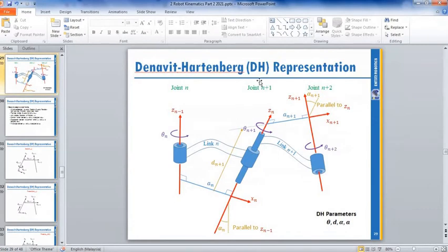Compared to the homogeneous transformation matrix, where you need to multiply: if you have 4 joints, you have 4 matrices. Depending on the type of joint, rotation or translation, your matrix always needs to be calculated if one of the motors changes position. So 4 matrices must be calculated every time your joint is moving.